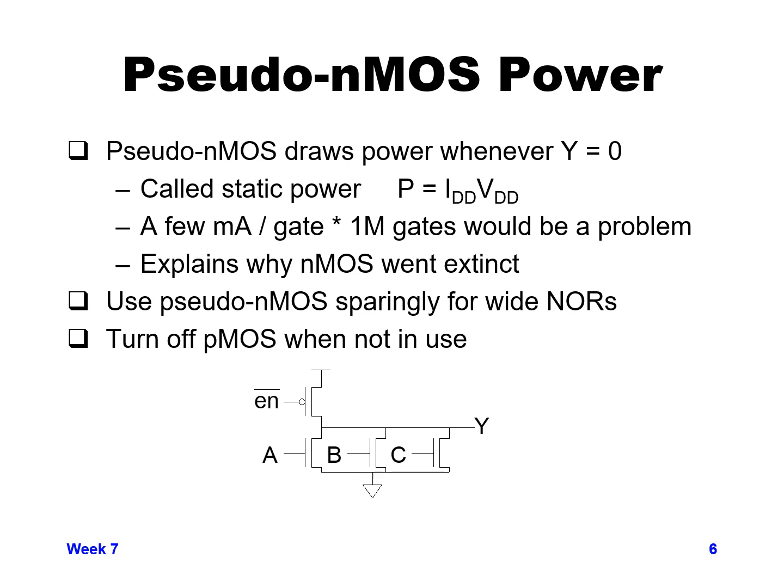But definitely, when you're not using pseudo NMOS logic, you want to either turn off the PMOS or make sure there's no static current flowing when you're not actually caring about the value coming out of pseudo NMOS. Because you do not want that constant power always being consumed, especially when you're not caring about the output value.